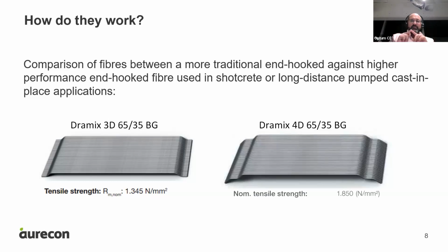But one, you can see here, has an extra hook, right? Well, an extra fold, and there's a significant difference in the tensile strength of this fiber. So when we started using concrete mixes, particularly internally, where we're designing things that need to last 100 years, and it might be less common in buildings, but in infrastructure, where we have to design tunnels that last 100 to 120, and we are moving now to mostly being the minimum 120.